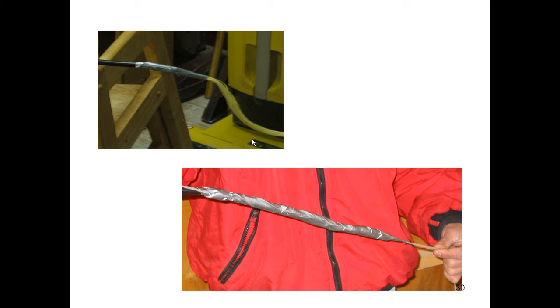And another hint for you, if you're doing this kind of thing, when we pulled this cable, the 800 feet, we had a 1,000-foot roll. We pulled it in, and when we got it to each end, the first thing I did before I terminated it is I cut off the first 10 feet and threw it away.